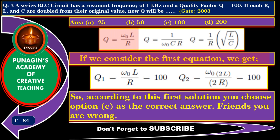If we consider the first equation, we get Q1 is equal to omega naught L divided by R, and this is given as 100. Let new value of Q be Q2, and Q2 is equal to omega naught into 2L divided by 2R, and again Q2 is equal to 100. So, according to this first solution, if you choose option C as the correct answer, friends, you are wrong. I will tell you why during the next discussion.